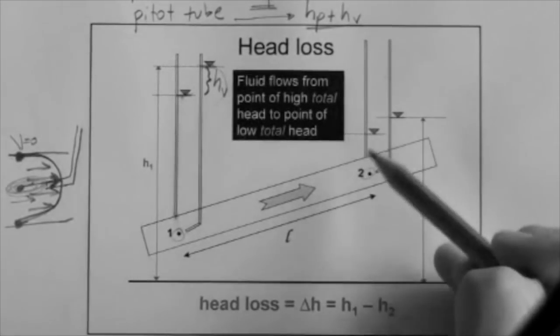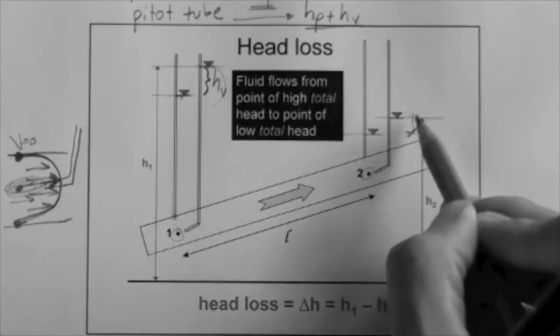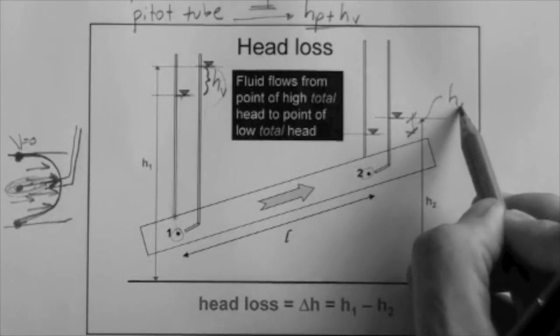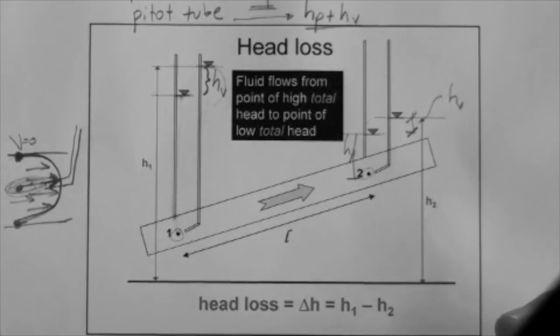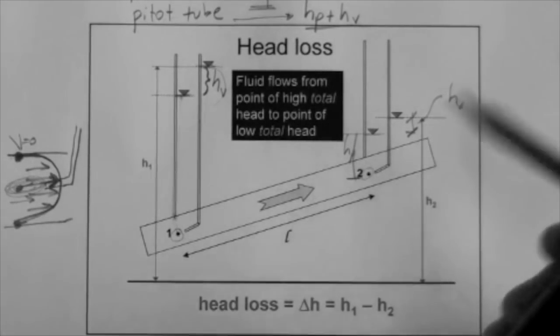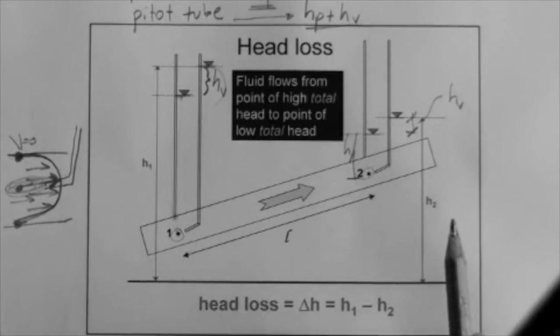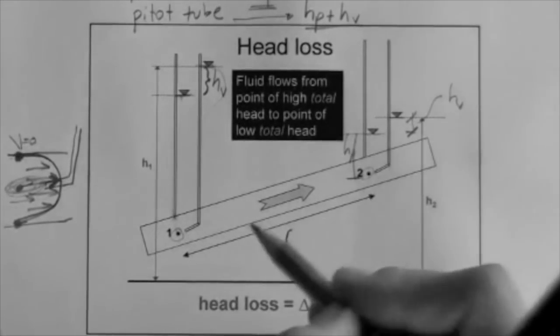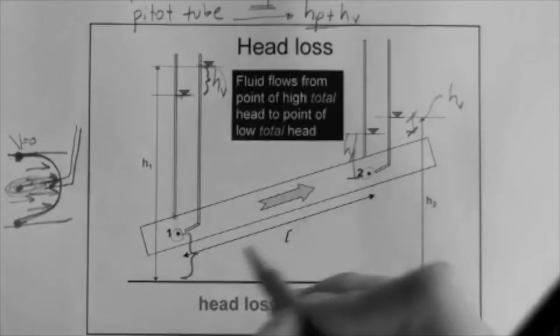Here we have the same thing. We have a pitot tube and we have a piezometer. That is the velocity head. That is the pressure head. Okay? So if we sum, well, before we get the total head, which is shown in red here, we should make sure that we complete everything by saying, look, the elevation head at this point is this.